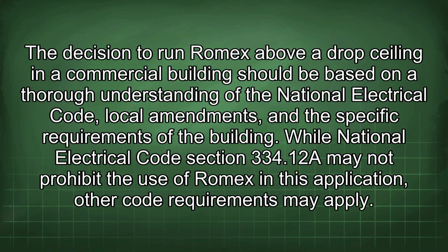The decision to run Romex above a drop ceiling in a commercial building should be based on a thorough understanding of the National Electrical Code, local amendments, and the specific requirements of the building. While National Electrical Code Section 334.12(A) may not prohibit the use of Romex in this application, other code requirements may apply.